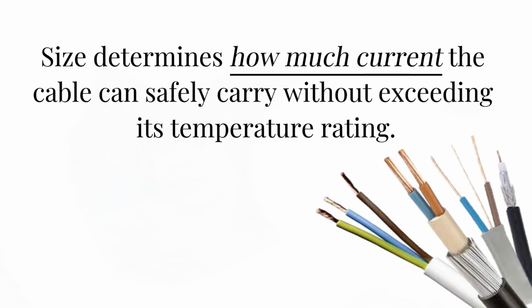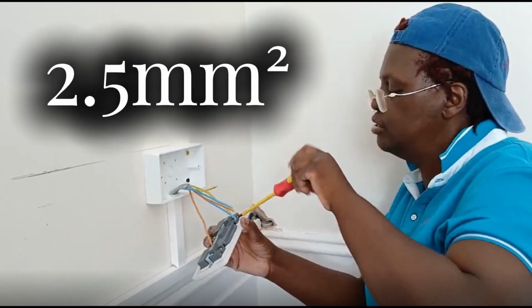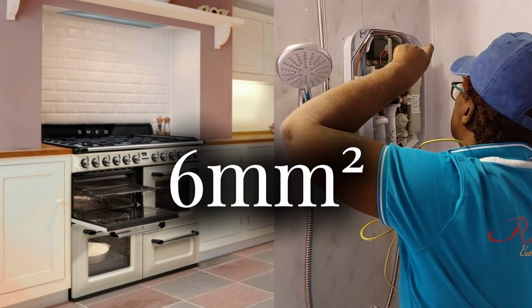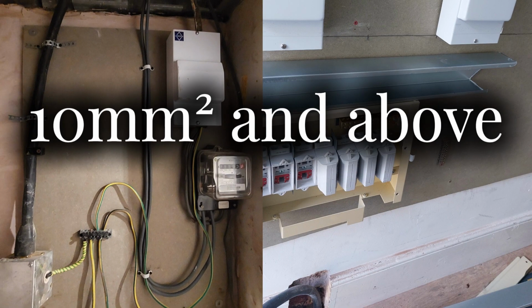That size determines how much current the cable can safely carry without exceeding its temperature rating. 1.0 or 1.5 square millimeters, lighting circuits. 2.5 square millimeters, socket circuits. 6 square millimeters, cookers or smaller showers. 10 square millimeters and above, sub-mains or high-load equipment.